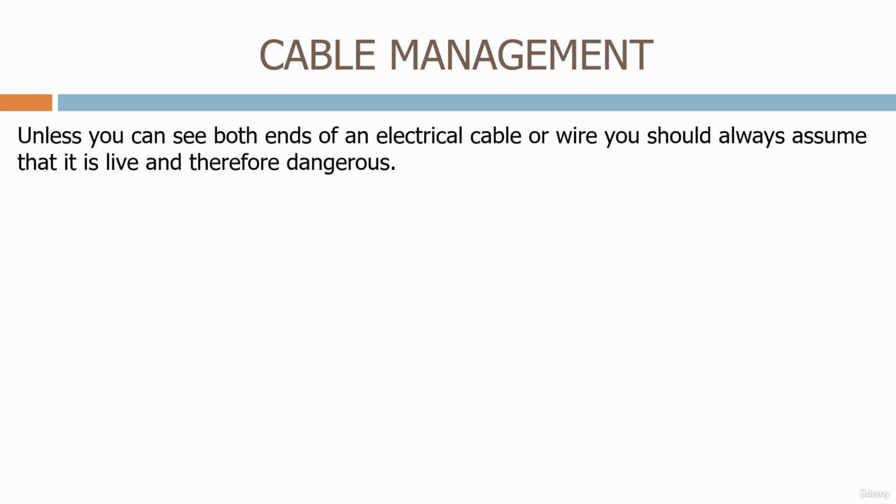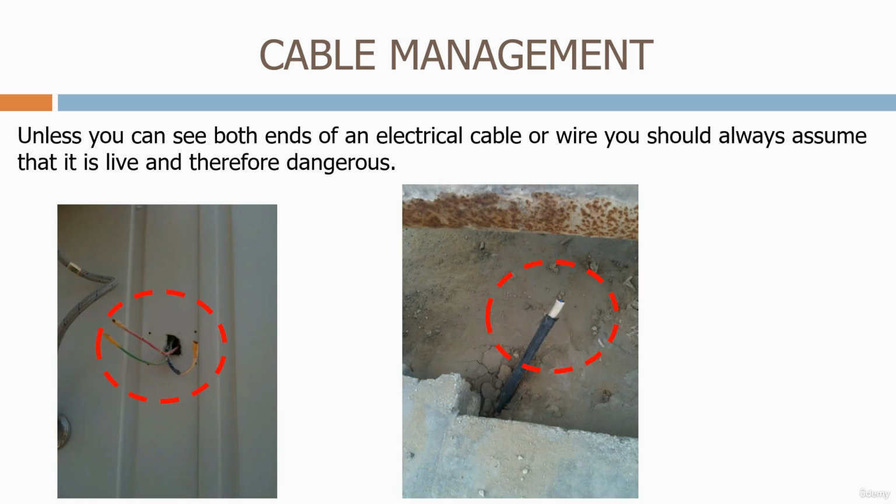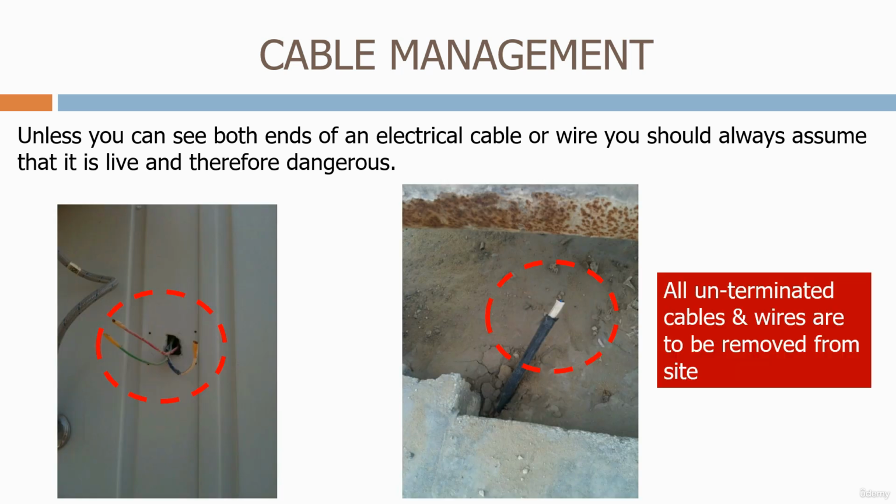Unless you can see both ends of an electrical cable or wire, you should always assume that it is live, and therefore dangerous. All unterminated cables and wires are to be removed from site.